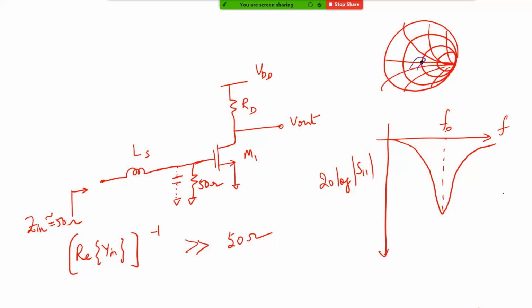That is to say that if you are sending some amount of power, the reflected power should be less than... I mean, the ratio of the reflected voltage and the incident voltage should be basically less than 1. If the reflected voltage is greater than the incident voltage, then it means that the circuit is oscillating and generating signals on its own, right? So that is the problem. That is why S11 and S22 have to be less than 1, and in the logarithmic scale they have to be less than 0 dB.